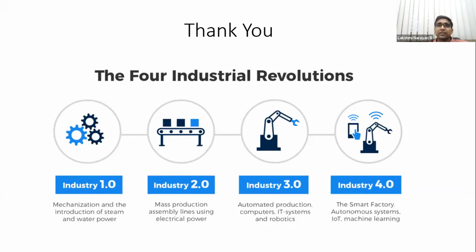So that was initially the understanding. After additively manufactured components, even if you do a very nice surface polishing, they saw failures occur, at least for fatigue as well as ductility purposes. These porosities were leading to fatigue cracks, and it's very, very clear. How we saw is that after the part failed, we look at the fractured surface, and we can see a very clear circular blob, and that blob has essentially caused the fatigue crack. So this is how we feel the porosity is a bad thing for all of us.